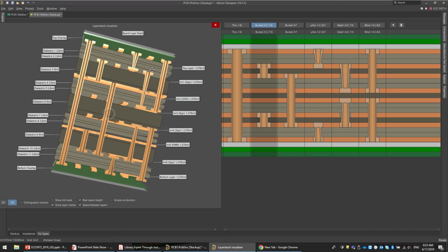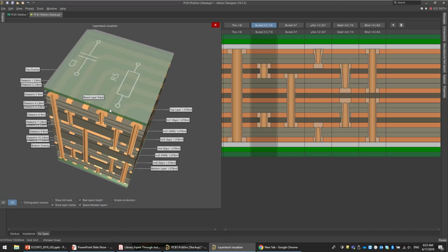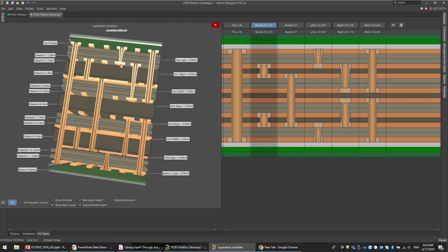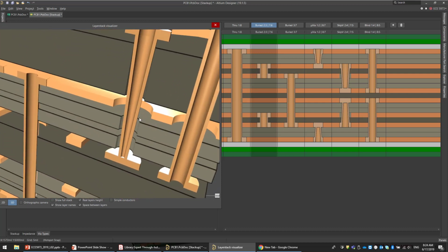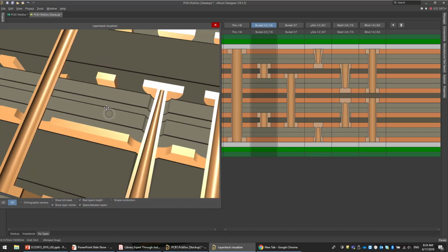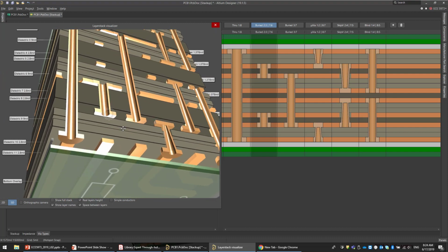We have this micro via in here. It's layer 1, you see how it connects with the trace and goes to layer 2, also connecting with the trace, and it's only accessible from these two. Then we have the mirror micro via from layer 7 to 8. We have the skip via in here, and this is the important point I want to show. You see how the via is skipped in here, so it's not connected with the layer in between the two. You see, that's why they call it skip via.